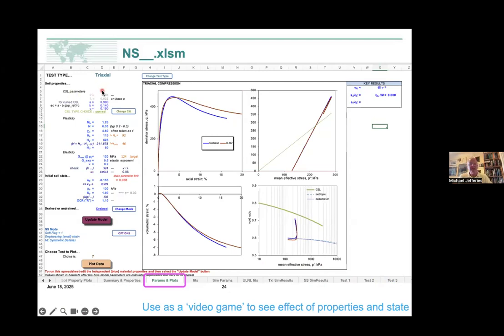Over here, these are our soil properties. So the M, the chi, the G's, the initial state parameter are all there. And these ones in blue are the ones we've come up with from assessing our lab data. This is what we've done from the Bender elements. And then, where do we get the state parameter from? Well, the lab has told us what the void ratio is. We've got our input critical state locus, and here I'm using a curved critical state locus. You don't have to limit yourself to a semi-log one. And we've used that for the state parameter.